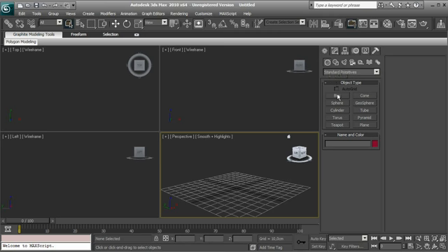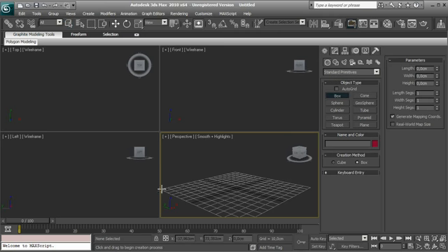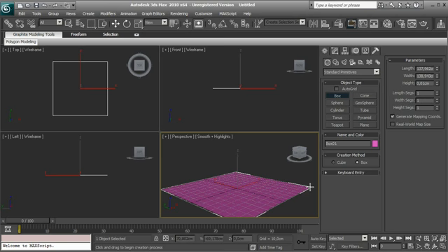Okay, now I can create a simple plane where our mesh can collide, and we use Reactor as the dynamic system. So the plane at the base of our environment must be a volumetric mesh, a 3D mesh. So I can't use the plane, but I have to use a box like this.